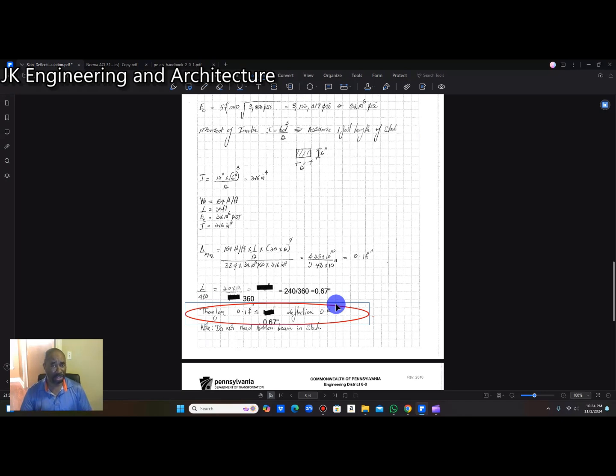And the reason why I'm doing that is out of an abundance of caution that we in Jamaica are in an earthquake zone. And if we get a violent earthquake of a certain magnitude, you want the slab to be stiffened so that it doesn't subject to damage. Okay, even though it is not showing that it is going to need a flat beam at the center, I will still put a flat beam there.